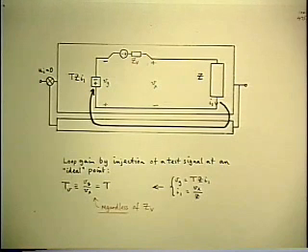So you don't have to inject a signal from an ideal source. Not only not nearly ideal, it can be a long way from ideal. Makes no difference. This is the key to measuring an actual unstable loop gain.